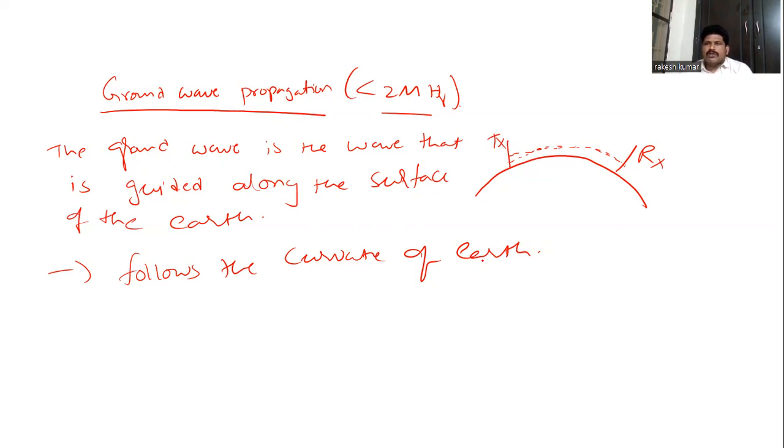This mode of propagation exists when the transmitting antenna and receiving antenna are close to the surface of the Earth, and supported at the lower edge by the presence of the ground. The ground waves that are produced by a vertical antenna are vertically polarized. That is, the electric field vectors of the electromagnetic waves are vertical with respect to the ground.